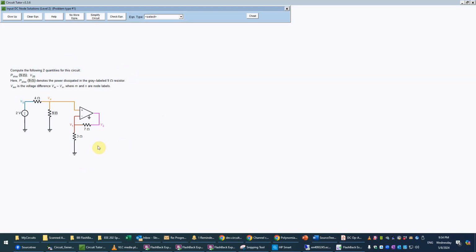And we can observe that we have a circuit with one operational amplifier pointing to the right here, with the two inputs, the positive and negative input, and the one output, whose current is basically indeterminate. And remember that these three different ground symbols, and for that matter the one that's connected schematically to the op amp, not directly but really via the positive and negative power supplies, which are not shown here, all those points are actually connected together by invisible wires here. That's standard convention in electronics, to use multiple ground symbols to avoid cluttering the diagram. And so we'll use that here.